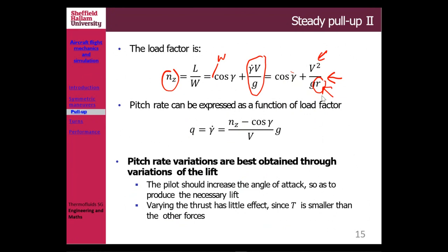Obviously, if you're doing a pull-up like that, then if the radius of the pull-up is smaller, you increase your G force or your load factor. Okay, so if you want to make it like a standard pull-up, then you have at least a radius that is big enough in order not to pull quite unreasonable G force in your maneuver.